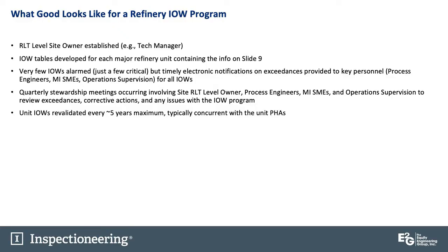I don't think you need to get people together to go through reams and reams of data and trends and charts and so forth. But efficient meetings identify the key risks, and efficient managers make sure that they got action plans to address those key risks. And another key aspect of a good IOW program is that they're revalidated every 5 years maximum. And I think it's good to tie these with the unit PHAs. It's a good package to review with your PHAs and helps make your PHAs more effective.